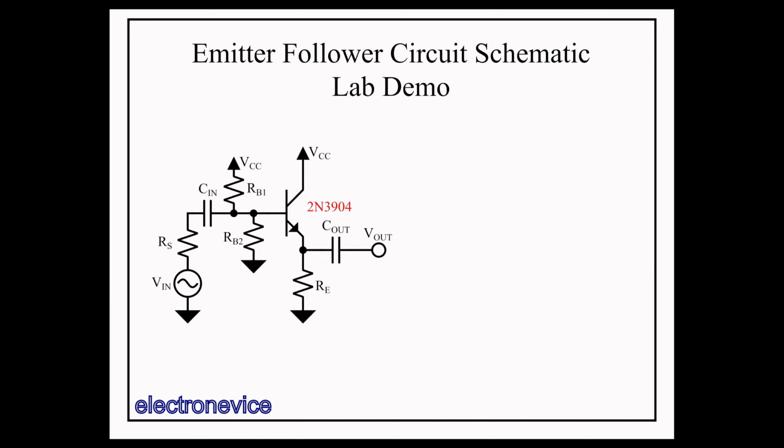There are many reasons to use a buffer, but one of the most important ones is when presenting a signal to an ADC. ADCs usually have some kind of sample and hold circuit on their inputs, which basically means there's a switch that connects the input voltage signal to a small capacitor internal to the ADC. The signal is periodically sampled by connecting the input signal to this small capacitor. Then the ADC disconnects the input signal from the capacitor in its hold configuration, where the capacitor stores the voltage that we saw on the input during the sample phase.